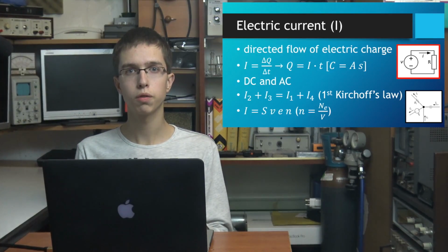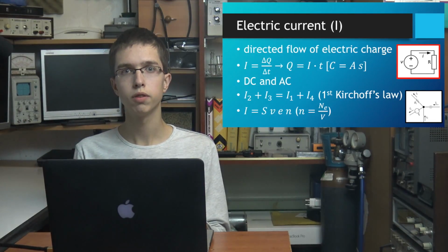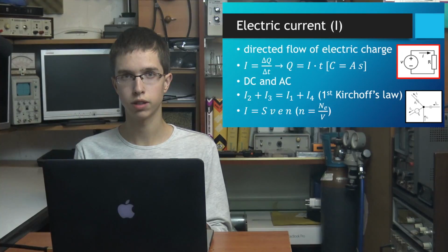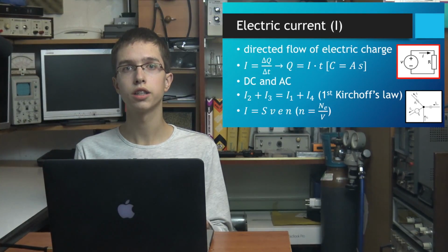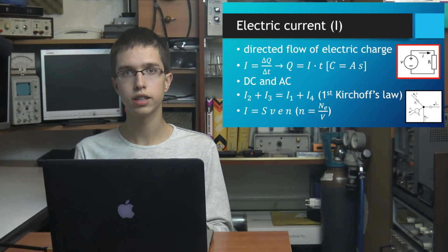So from the equation of conserving of electric charges Q, we have that Q2 plus Q3 is Q1 plus Q4. We've got equation for conservation of electric current. So the same thing, but for I2 plus I3 is I1 plus I4, when the first one is divided by time interval delta T. We can also say algebraic sum of currents in a node is equal to 0, and it's marked using sigma notation, where is indicated that there is number of currents whose sum is 0.